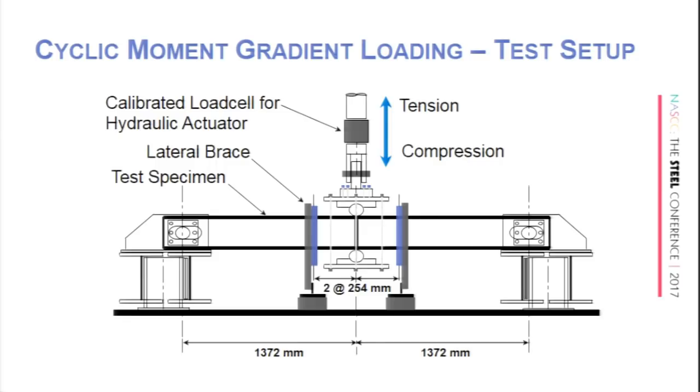Do you think the length of the beam is the same length it was when it ended with the local buckling? That beam's going to shorten. Do we know how much it's going to shorten? Well, we've never measured it before because no one ever really thought about it. It's really simpler to do this experiment by taking half the length of the beam, welding it to an end plate, and pushing on the cantilever end. But you're really doing a connection test and not a beam test. So we developed this system to do simply supported beams.